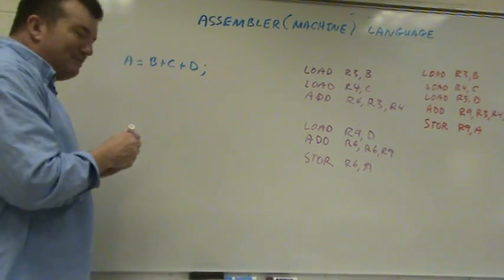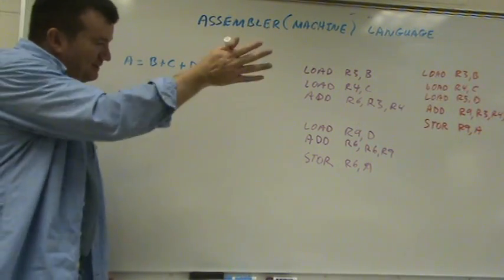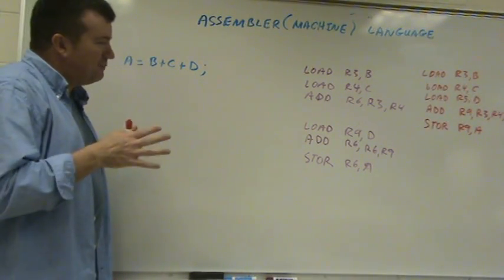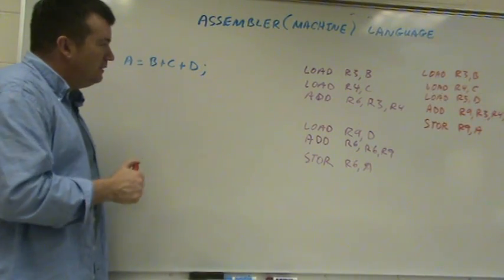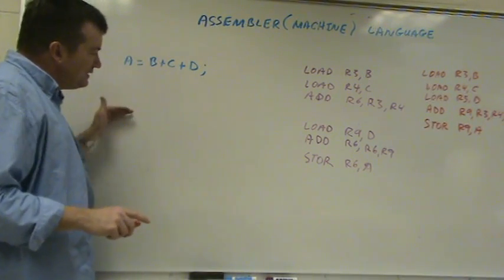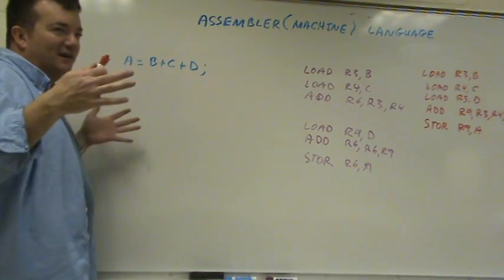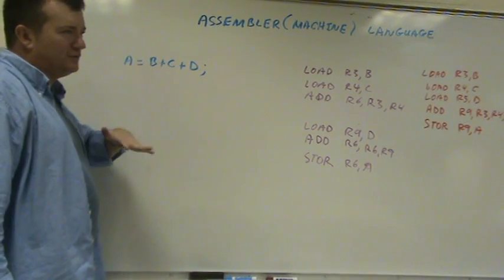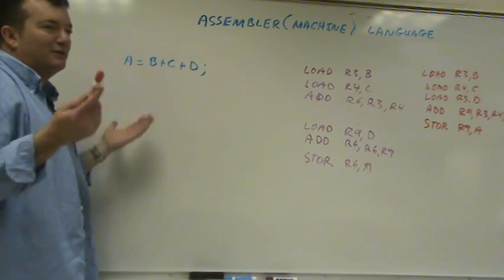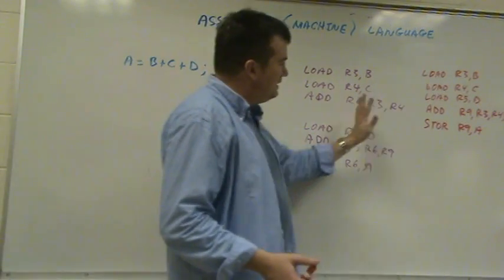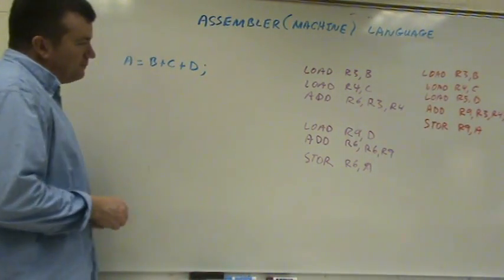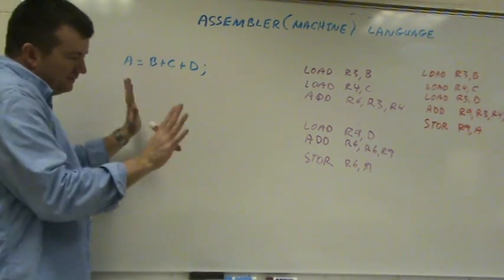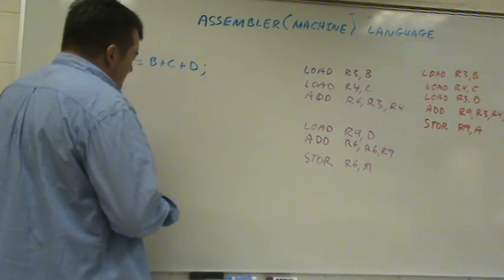But the problem is that piece of hardware, I mean, we could, as a homework assignment, come up with something that takes 3 registers and adds the results together. But you can imagine it would take longer to do. Since it takes longer, that execute step would have to be given more time, and therefore we're slowing everything down. Now the fetching, decoding, and storing steps are given unnecessarily more time because we've added a new piece of complicated hardware. But then we could try that trick to maybe cut the execute step into 2 parts, and then we'll get a better result. So there's kind of a trade-off.